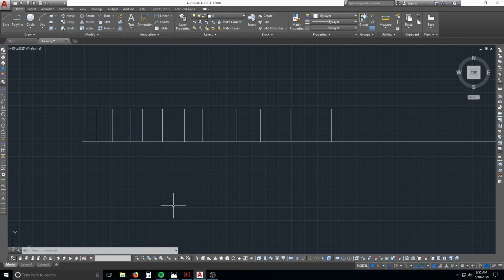What else can you use that for? The fence command, you can use that in a couple other commands too. For the life of me, I can't remember off the top of my head, but yeah. So learn that one. That's a very important one. Trim, and then utilizing the fence command within the trim command as well will really help you out.